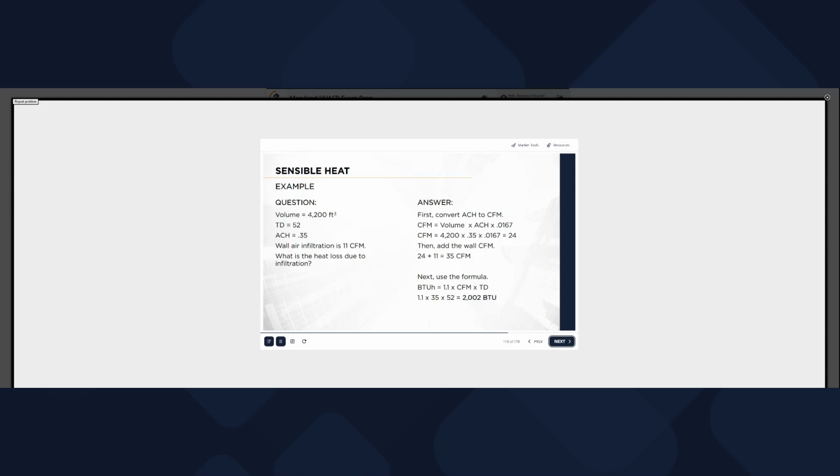First, convert ACH to CFM. CFM equals volume times ACH times 0.0167. CFM equals 4,200 times 0.35 times 0.0167 equals 24.